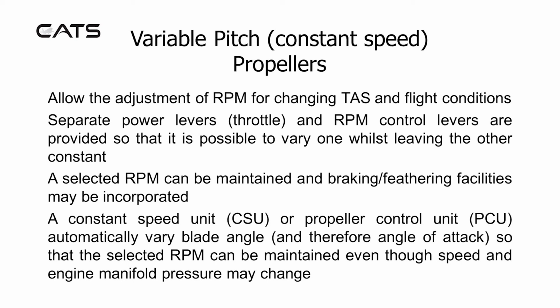A constant speed unit or propeller control unit automatically varies blade angle and therefore angle of attack so that the selected RPM can be maintained even though speed and engine manifold pressure may themselves change.